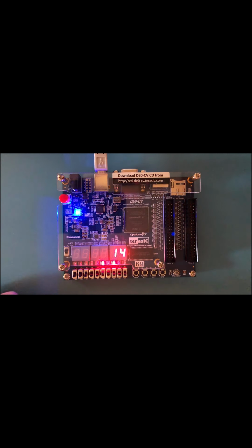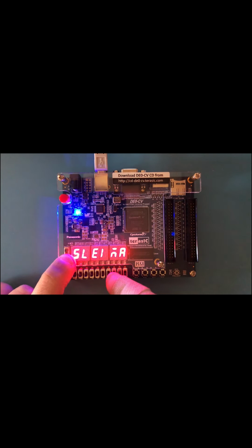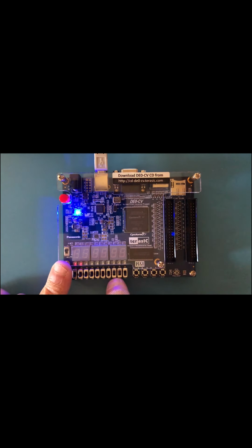The second part is we're going to do the same thing, but step by step. So let's put switch 1 on, turn off all these switches, reset it, and then go back. Any combination that is not allowed makes the display turn off. For instance, switch 2 being on and switches 3 and 4 off is not an allowed option, so it turns off. Now switches 2 and 3 are on, so we can see where the counter is, and we are at the first instruction in the ROM memory, at 0, 0.